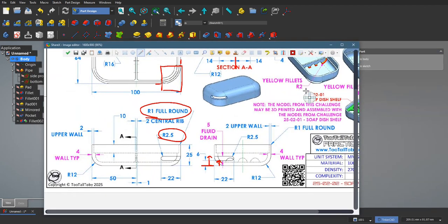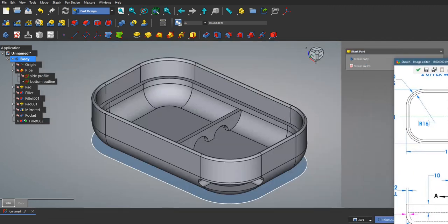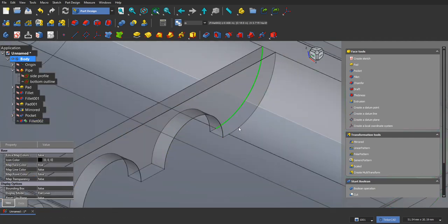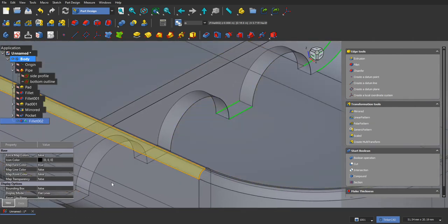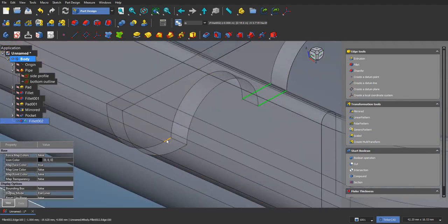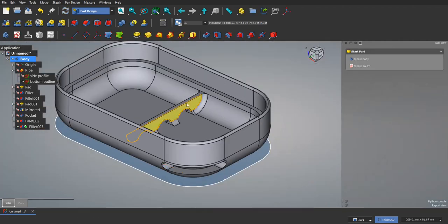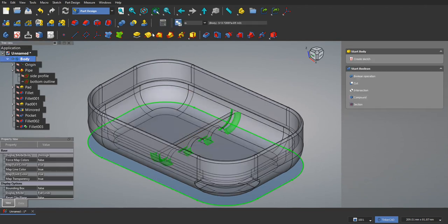Let's take a quick look. So there are these yellow fillets. So I'll go and add those quickly. So I want this line here, and once again, tangent propagation is always on by default. I actually don't know if you can turn it off. I'll create those 2mm fillets. And now get my FreeCAD toolbar, select the body,